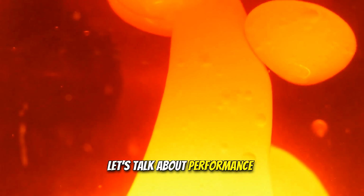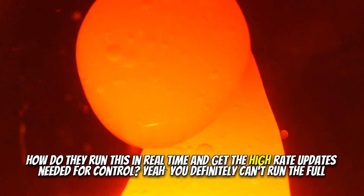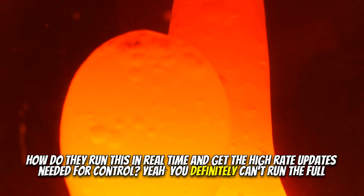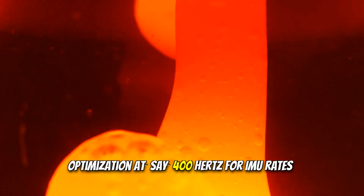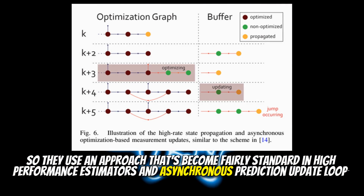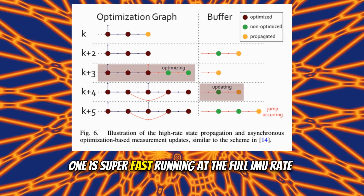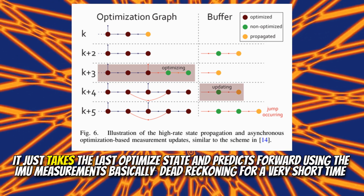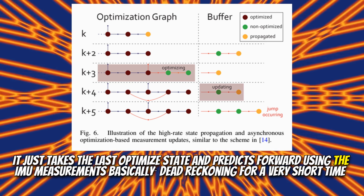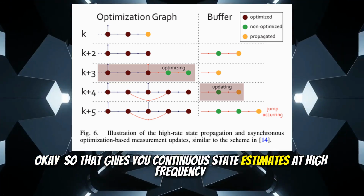Let's talk about performance. Factor graph optimization, especially with all these extra variables, sounds computationally heavy. How do they run this in real time and get the high rate updates needed for control? Yeah, you definitely can't run the full optimization at, say, 400 hertz for IMU rates. So they use an approach that's become fairly standard in high-performance estimators, an asynchronous prediction update loop, meaning you have two loops running. One is super fast, running at the full IMU rate. It just takes the last optimized state and predicts forward using the IMU measurements, basically dead reckoning for a very short time. Okay, so that gives you continuous state estimates at high frequency.